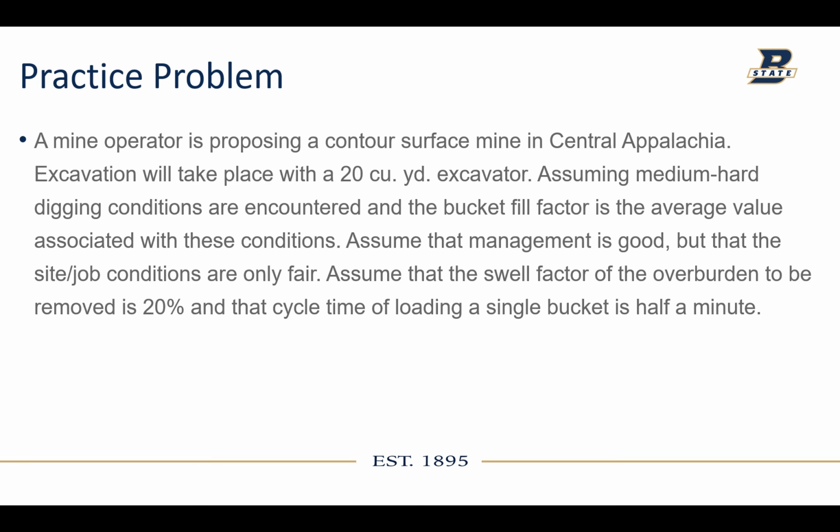So we have a practice problem here. A mine operator is proposing a contour surface mine in central Appalachia. Excavation will take place with a 20 cubic yard excavator. Assuming medium hard digging conditions are encountered, the bucket fill factor is the average value associated with these conditions. Assuming that management is good, but that the site or job conditions are only fair. Assume that the swell factor of the overburden to be removed is 20%, and that the cycle time of loading a single bucket is half a minute. A nice good average.